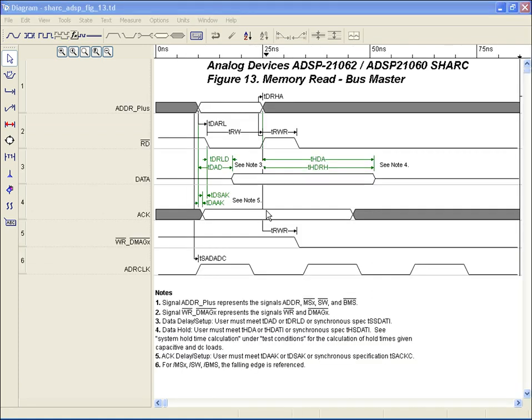Just a note about naming waveforms. TimingDesigner allows just about any character string for a waveform name. However, it's strongly recommended that legal HDL waveform names be used so that any future reference of a waveform from a derived signal will respond correctly. TimingDesigner supports Verilog or VHDL syntax for derived signals, so any reference of an existing waveform in a derived signal equation must be syntactically correct in order for the derived signal to be evaluated properly. Derived signals and clocks will be covered later.